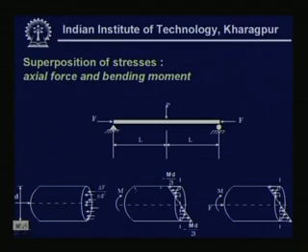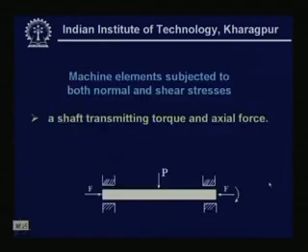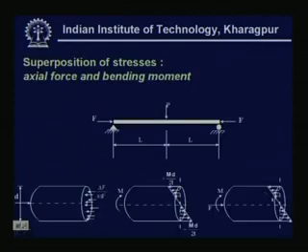Added together, this will be a compressive load. So, the total is minus, and the other side is plus and minus. That means you are getting an effect of this manner. So, the net stress will be what? Delta F by pi d square, and I think this would be 4 actually, and this will be Md by 2I. If you add this together, then you get the total stresses. Add up means the algebraic summation.